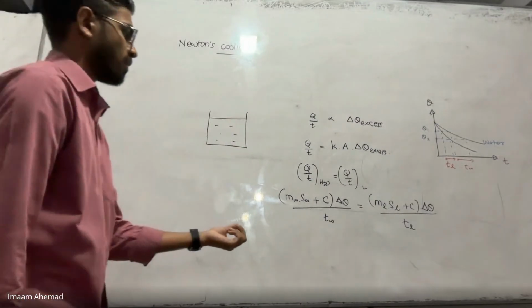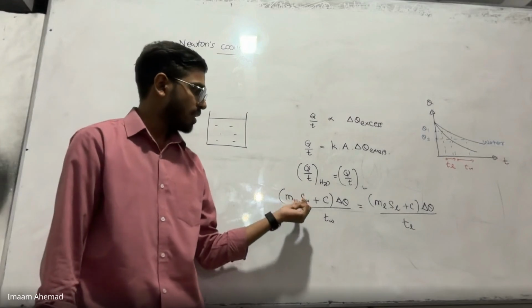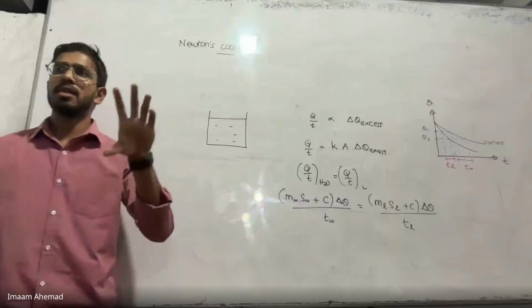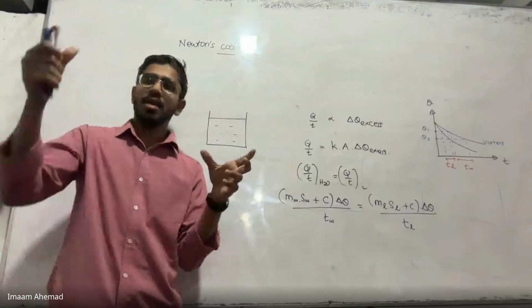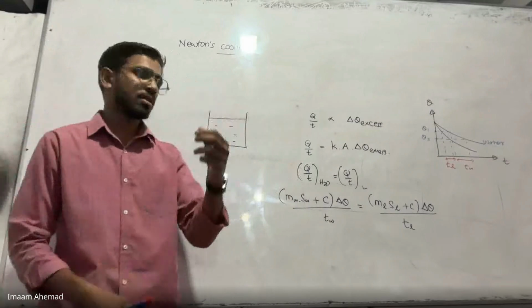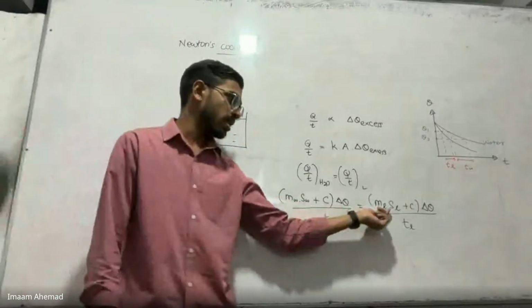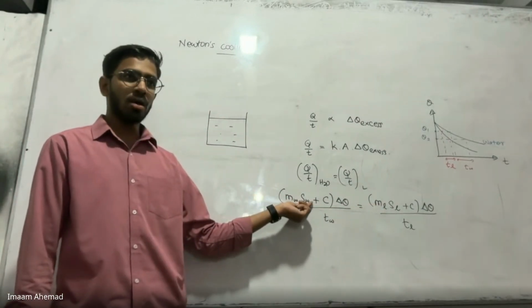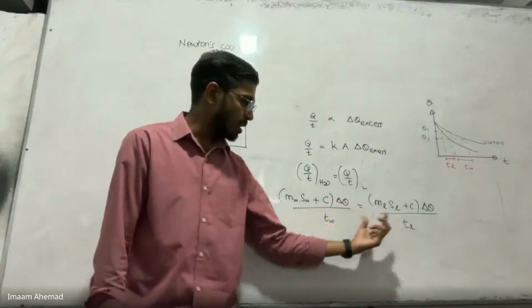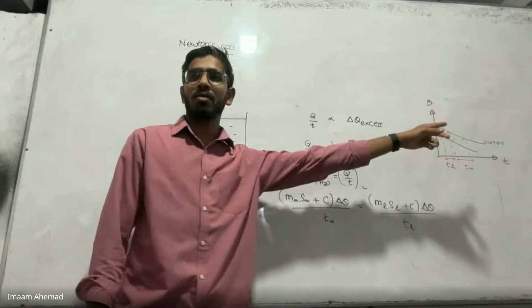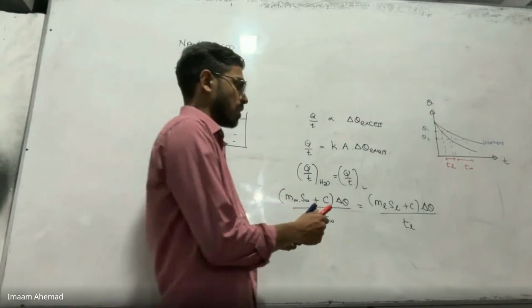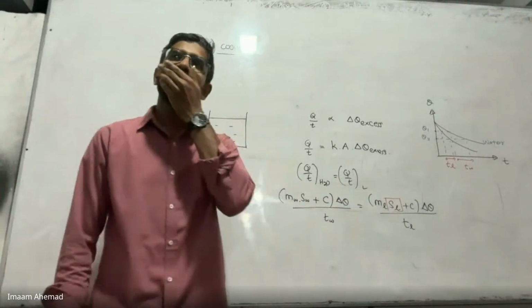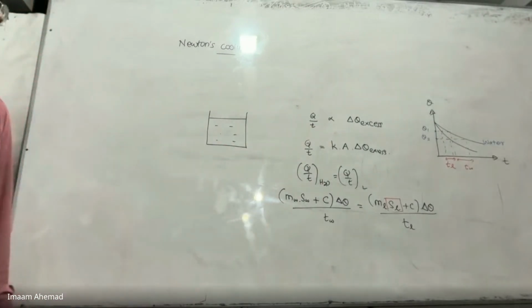Once we know those, we can find M_W and M_L, finding the mass. It's similar, right? First, we take the weight of the calorimeter and stirrer only, then add the water and get that weight, and get the difference. That will give us this mass, and similarly the other mass. So these two are known. Then S_W is known, C is known, and T_W and T_L can be got from the graph. So everything is known except for this. From this experiment, we can calculate the specific heat capacity of that unknown liquid.